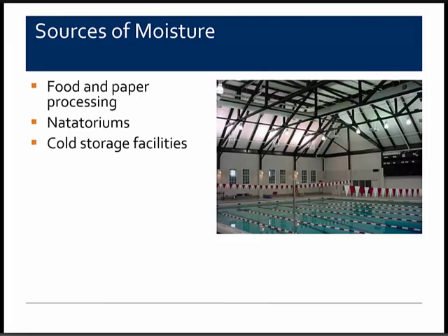You want to limit the sources of moisture. In one of the earlier slides, we talked about adhesive failures due to moisture in the deck or substrates. There are food and paper processing structures that generate moisture that drives through the deck.